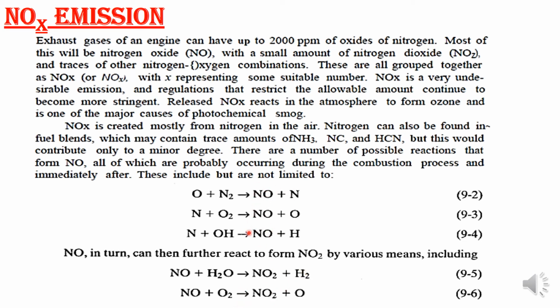For NOx to be formed, the two strict conditions are availability of oxygen and high temperature. All the reactions that are formed depend upon the temperature and availability of oxygen. Remember, high temperature and availability of oxygen are the two main reasons for the formation of NOx. When the proper amount of oxygen is available at high peak combustion temperature, then more NO is formed through these three steps, and NOx is formed as the atmospheric gas NO oxidizes.